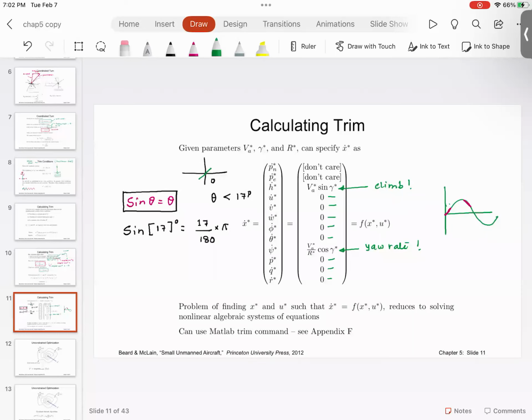But if you go 20, 25, 30, 35, 40, 45, this assumption is not valid because you will have to find the linearization about the operating point that you are linearizing. Everyone understood this? So first and foremost, find out the trimming or operating point, and then linearize so that your model will be good.